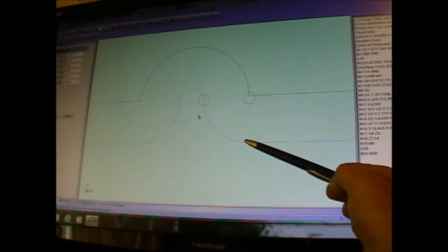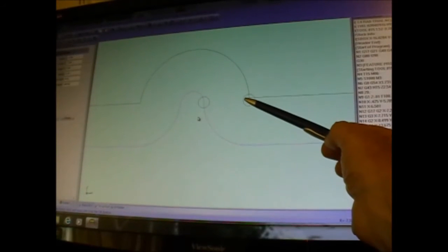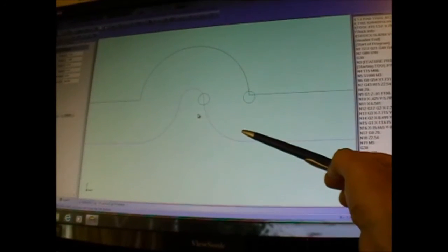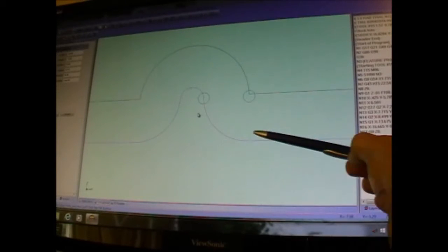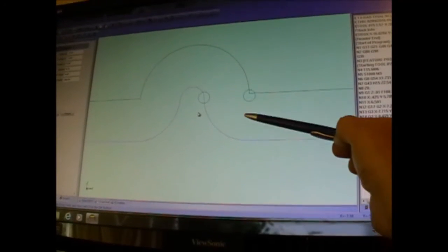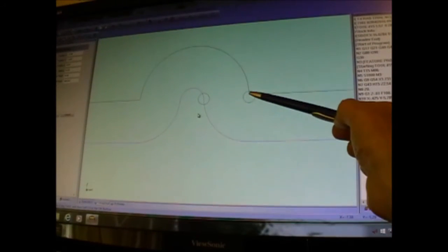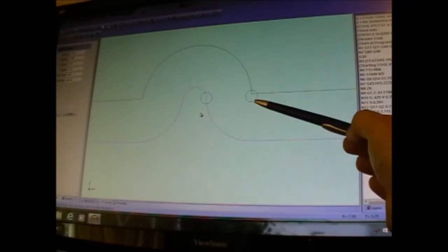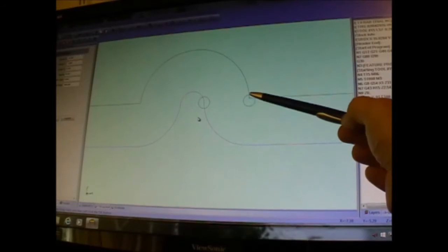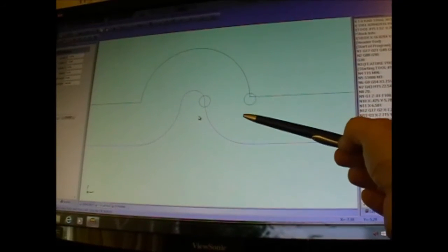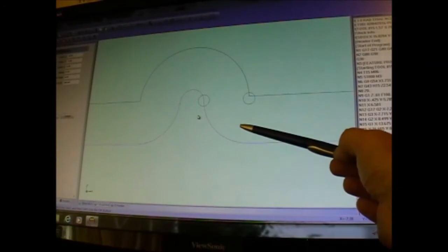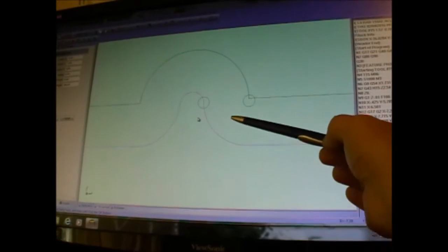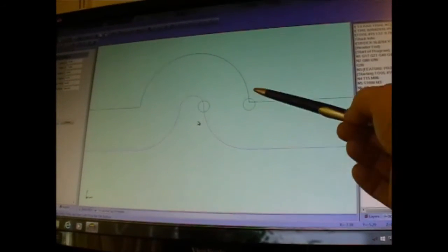There is an offset for the center point of the arc of, in this case, 0 in this direction and this amount in this direction, and that's the I and the J amount. Now you need to understand that well enough so that when you're doing the transferring of your code, you transfer the right values with the right code identification.